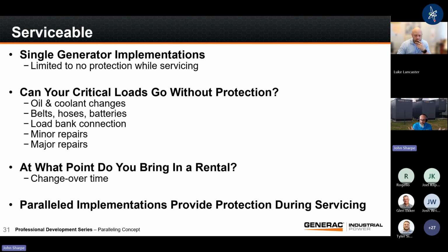Taking maybe 1,000 kW portable generator and bringing it in and tying it to your building, where are you going to tie it in? You tie it into the main switchgear? Are you going to pull the feeders off of the generator and splice onto those? How do you even do that? Becomes a pretty involved thing to bring in a temporary piece of equipment if you had to. Having that redundancy eliminates a lot of that conversation.